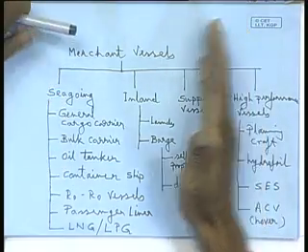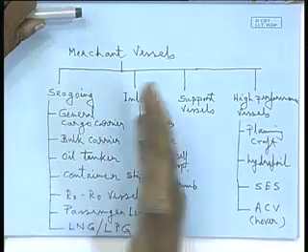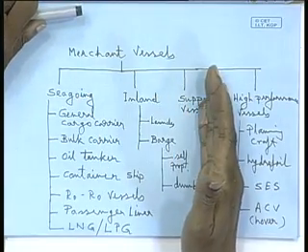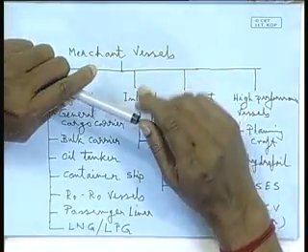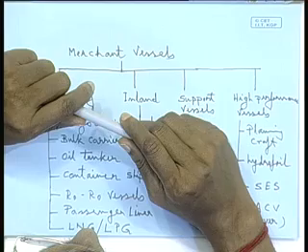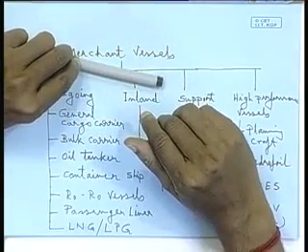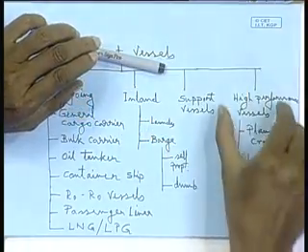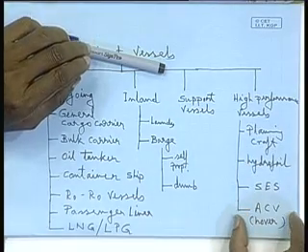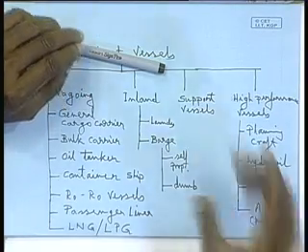All the vessels we have seen, the sea-going vessels, the inland vessels, the support vessels, are supported by buoyancy force only, following the great Archimedes principle. But when high performance vessels are cruising, part of the weight is supported by a lift force, similar to that of an aircraft.